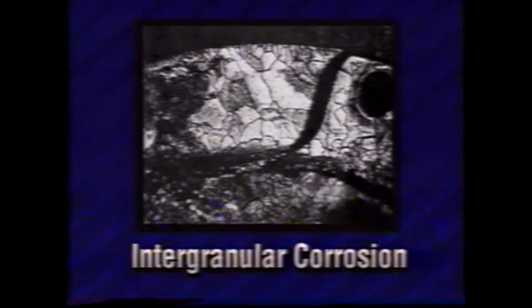Intergranular corrosion is the preferential dissolution of grain boundaries or the zones immediately adjacent to the grain boundaries. There is little or no attack on the main body of the metal grains themselves. In general, the grain boundary materials are more active chemically than the grains. This is because the boundaries represent areas of mismatch between the orderly and stable crystal lattice structures between the grains. Preferential attack is enhanced by segregation of specific elements or phases.